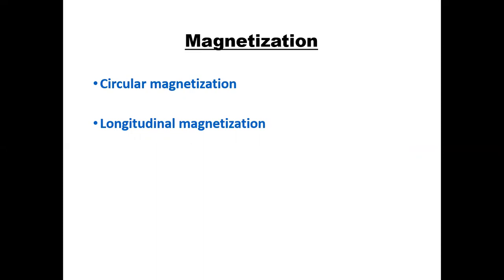In that case, if there is any discontinuity, then lines of force will leave the job and come out, and we get flux leakage, and so the formation of north and south poles. If you apply iron particles there, then the iron particles will accumulate because of the dissimilar poles, and we get an indication. So this is the complete principle of magnetic particle testing.